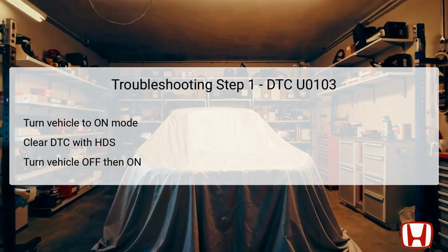This procedure ensures that any residual codes are cleared, allowing you to check for new or pending DTCs. If DTC U0103 reappears, that confirms the failure still exists, and you should proceed to the next troubleshooting steps.